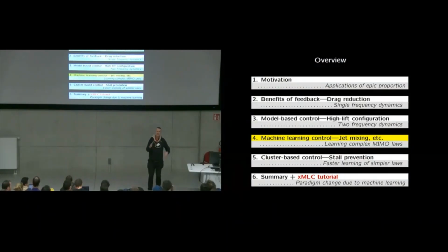So if you take the base flow and the fluctuation, u0 and u prime, it's linear. It has to be in the linear term. Now you look at the other linear term, so nabla u prime u0. It's also a linear term. So there's a linear part of the convection term, which also goes into the linear term. And then there is a residual part, so nabla u prime u prime. Essentially, if you average this, it would be the Reynolds stress. So this part goes into the quadratic term.